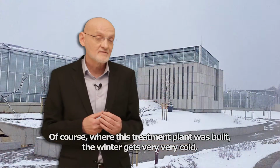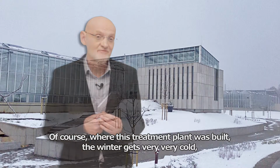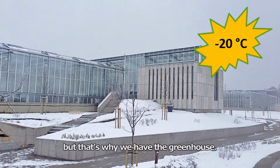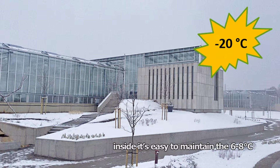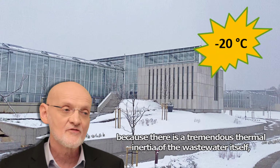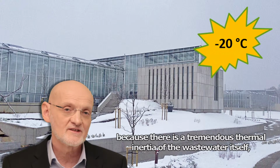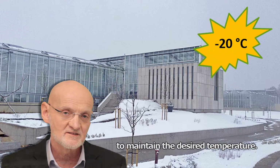And of course, where this treatment plant was built, the winter gets very, very cold. But that's why we have the greenhouse. So even when the temperature outside drops below minus 20 or 25 degrees centigrade, inside it's easy to maintain 6 to 8 degrees because there is a tremendous thermal inertia of the wastewater itself. So very little additional supplemental heat is needed to maintain the desired temperature.